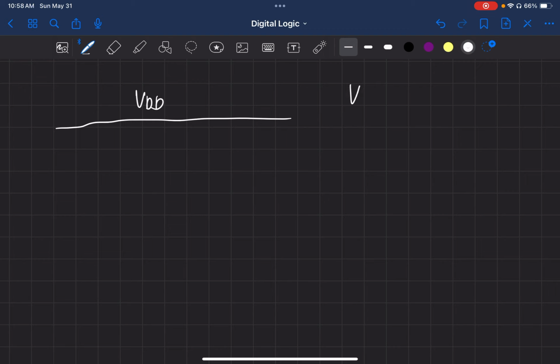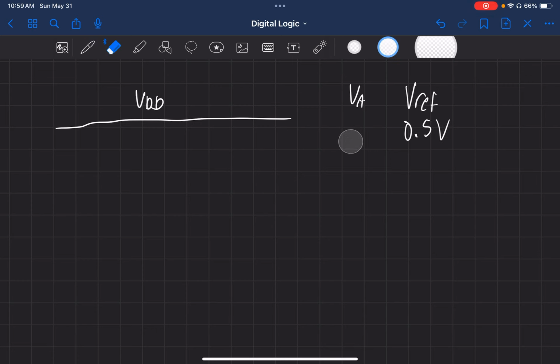So usually you'll have the cell line. Well, I don't know what to call that. We'll just call that VA, and then we'll have a VREF or something. And then VA is some sort of capacitor value that's not quite one, not halfway. We have this VREF that's half of the total voltage. So let me be more clear about this. We'll keep the numbers simple. So like VA is 1 volt, which is pretty close in some memory chips. Then VREF will be half of that, so like half a volt. And we have that as a reference because, of course, VA could be 0 volts.